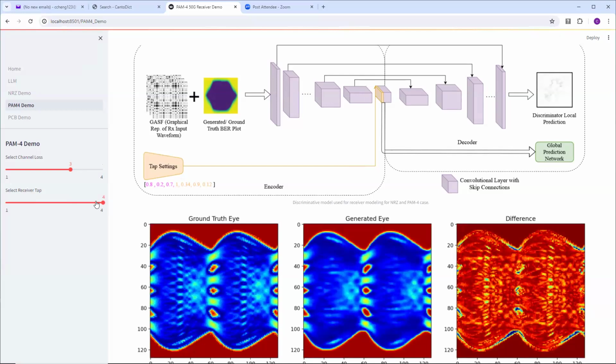Most of the slowness of the display is controlled by, first of all, we have an internet. Second of all, the image itself takes time to load. If you look at the raw image itself, it takes about 200 something milliseconds to generate the data itself. If you compare with any PAM4 simulation using a regular CAD tool, it will typically take about 5 to 8 minutes to generate a PAM4 eye diagram. So it is significantly faster in speed, right?